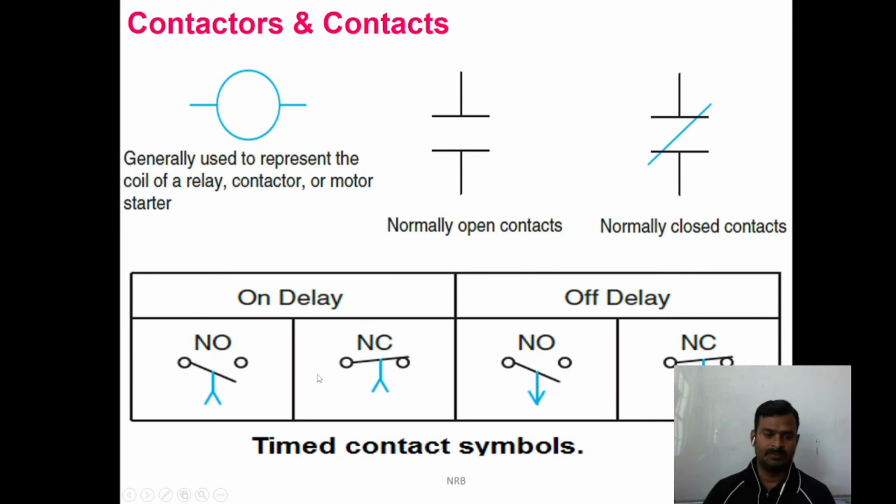So with the on delay timer, at the beginning of a process, if you want to start a motor after a few seconds, say for example, if you want to cut some metal, first for 5 minutes or 2 minutes you need to put on a lubricant. After cooling that particular area, then you will start the cutting machine or cutting operation. Many sequences are like this. First, you need to cool down or bring about that particular situation, then later you will switch on the second one.